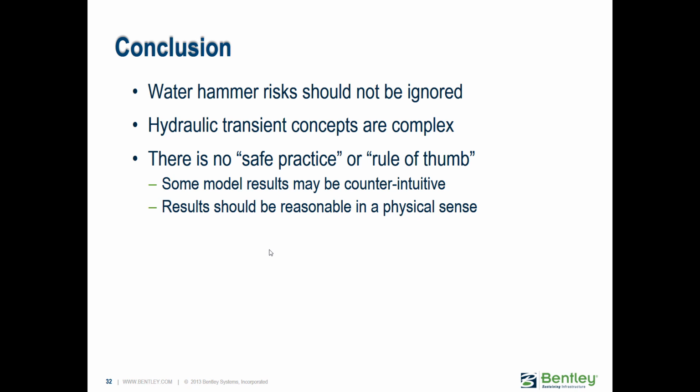And lastly, there's not really any safe practice or rule of thumb. It's really not worth just running through the Joukowsky equation and saying, okay, I'm good. Sometimes there are things that you may not realize will be happening, and complex interactions that can occur, and if you don't do a transient simulation, then you could be putting your system at risk.